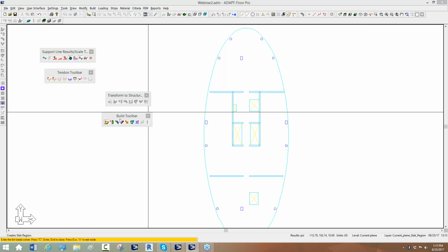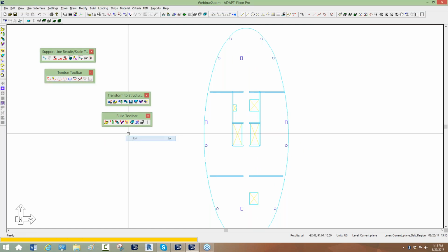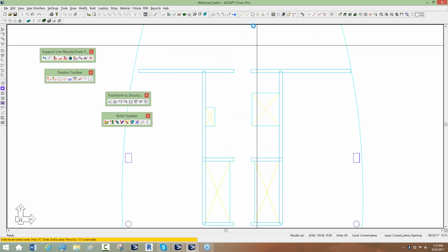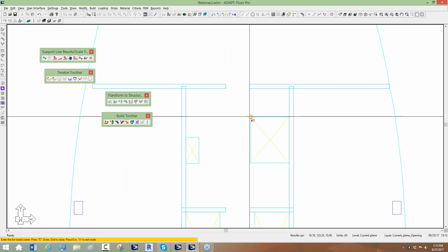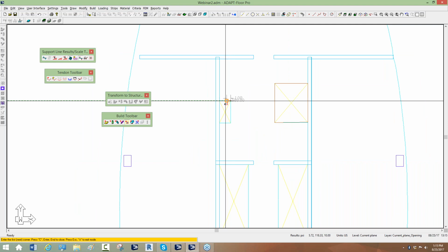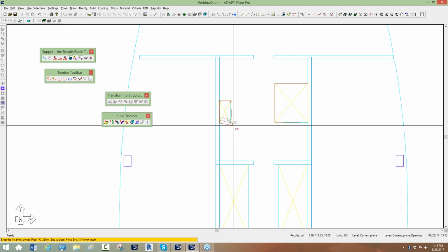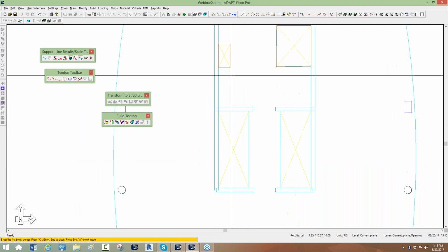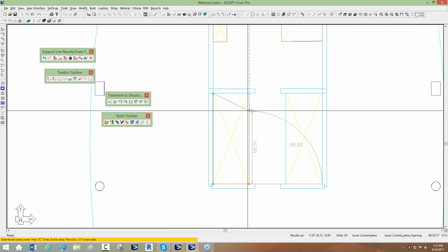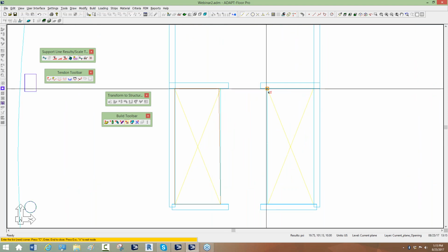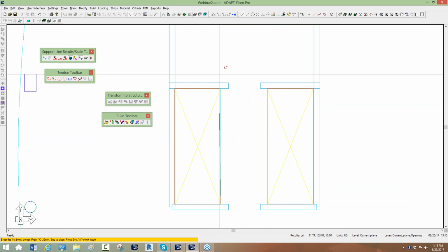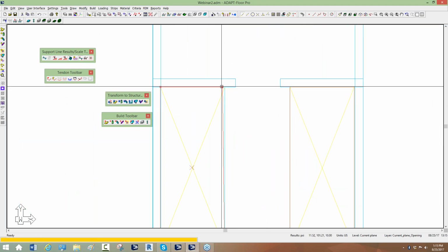Now I'll build my slab, or excuse me, my openings. Let me just exit out of that. I'll go to opening, and I'm going to turn off a few of the snap tools there, and just draw in my openings. Now again, this process could be much faster if we have transformable entities in the CAD file. In this case, we do not, so we're having to do a combination of both from-scratch modeling and conversion from the CAD file.